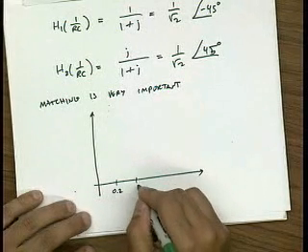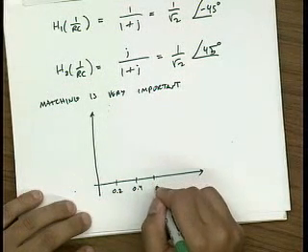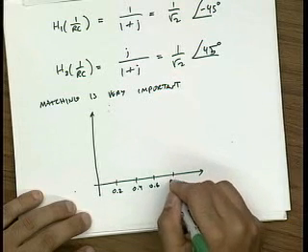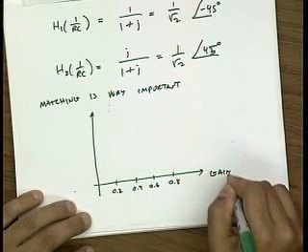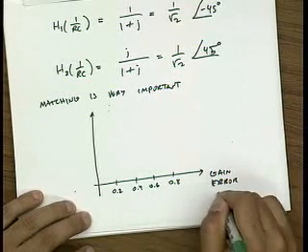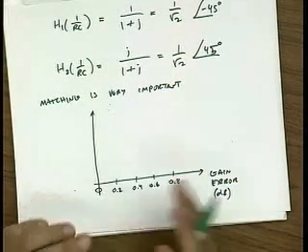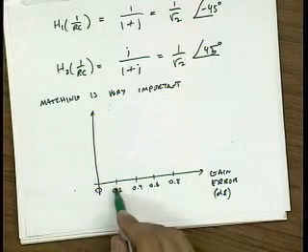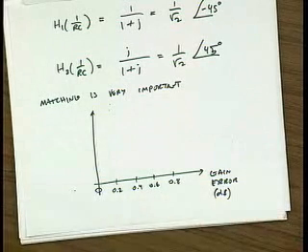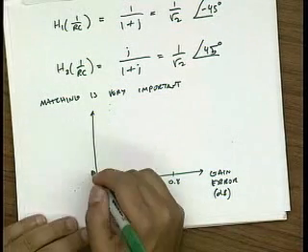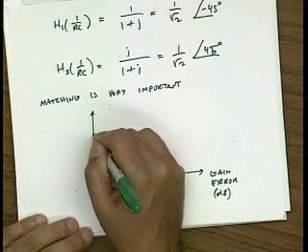On the x-axis, I'm going to draw the amount of gain error. Let's call this the gain error in dB. So 0 dB means there's no gain error. Both paths have the same gain. 0.2 dB means that one path has 0.2 dB more or less gain than the other.